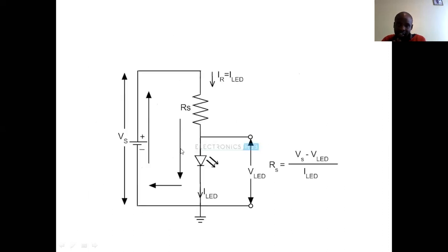So this is just a circuit diagram. You can see the applied voltage here. Then of course it has a resistor which protects it, especially in case the voltage is too much. And it is in forward bias. So basically, as current flows through, or as this voltage is applied and it overcomes the potential barrier, it emits your light.